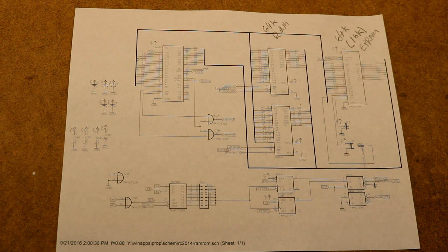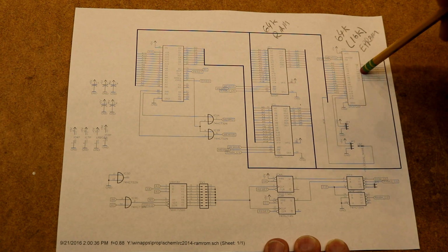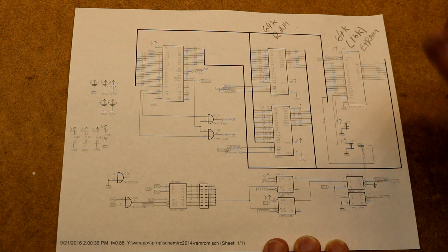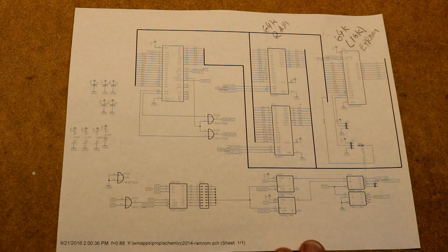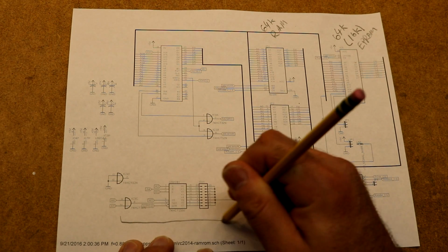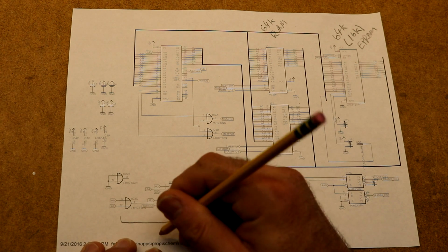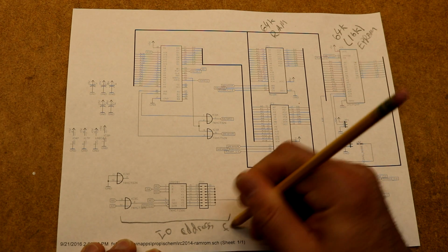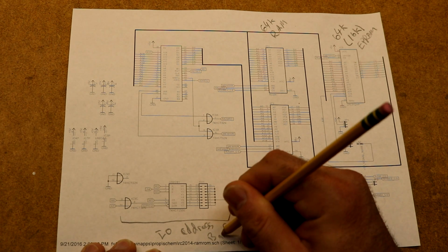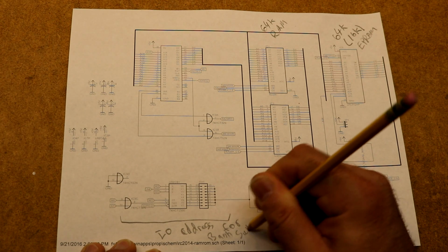And when we write a number, 0, 1, 2, 3, or 4, it will select between the EEPROM, the lower RAM chip, or any of 2 external RAM chips that we could want to page in. We're not going to actually use those external RAM chips, but pretend we could, and then we could have a 128K computer if we so desired. So this here does the I/O address for bank switch.